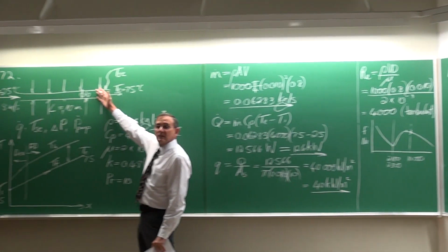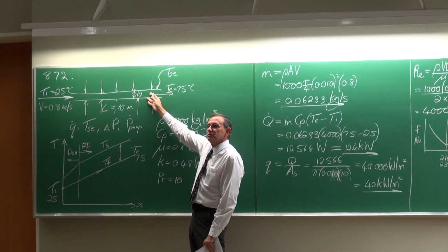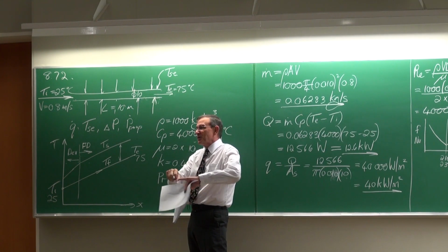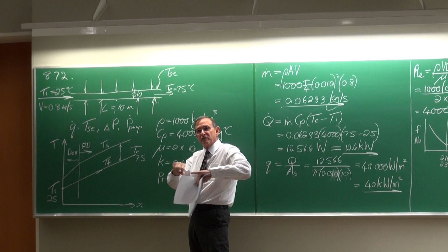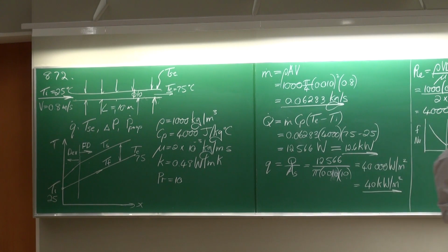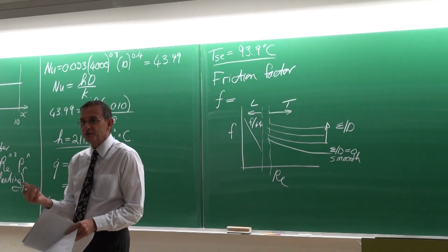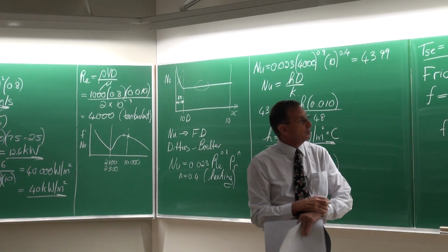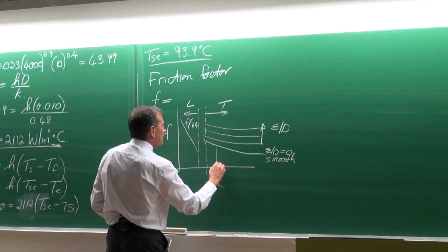Normally, except if it is specified differently, we will assume it's a smooth tube. And your question would be, is that a good assumption? And the answer is yes. Any copper tube or steel tube these days is being made from hard-drawn or soft-drawn tube, and you can go and measure it. They are really, for all practical purposes, smooth. In the old days, when the tubes, which were then called pipes, were cast, they were very rough on the inside. But these days, for all practical purposes, you can assume they are smooth. And that's what we're also going to do. So that's now very easy.